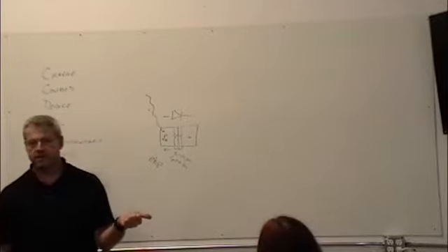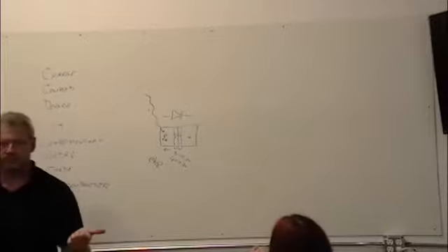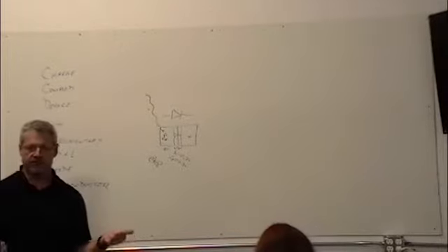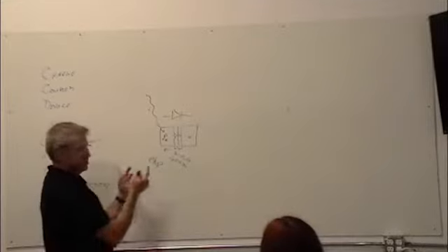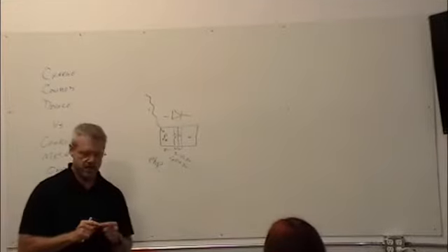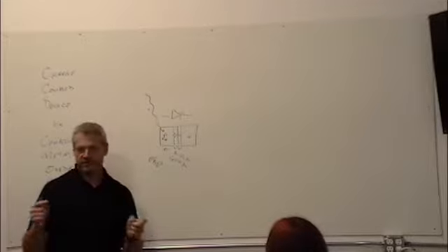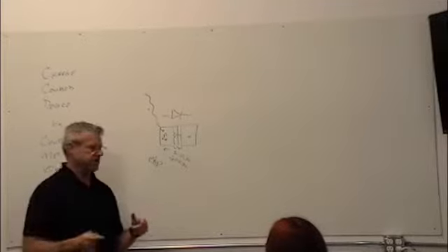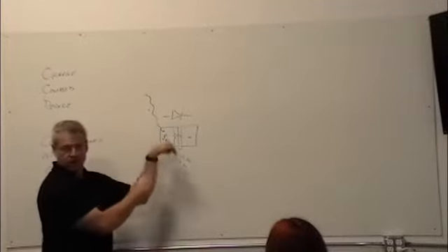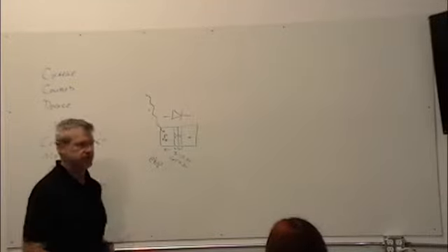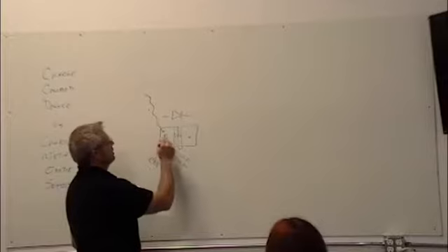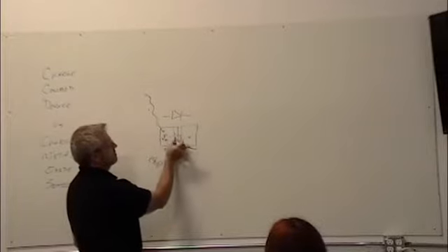Well, there's a diffusion lifetime based on temperature and everything else, and because that diffusion lifetime is relatively short, they usually just fall right back into each other. There's also the diffusion length is based on the diffusion lifetime. They can't get very far. Each will want to pop in and pop out, and everything's happening. It just recombines and you don't notice it. The thermal energy that's causing this to happen is what causes this.